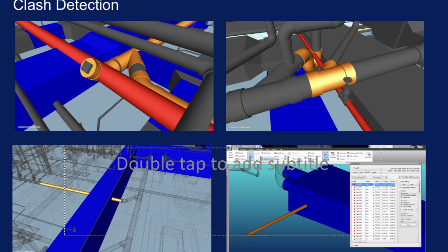So from that point, you can detect early the possible clashes during the early stage of the project. For example, here you can see that the plumbing, the ducting, and the fire protection lines are clashing on a specific area. So you can notify the designers right away: we need to move these pipes, or you need to change the elevation of the duct, for example.